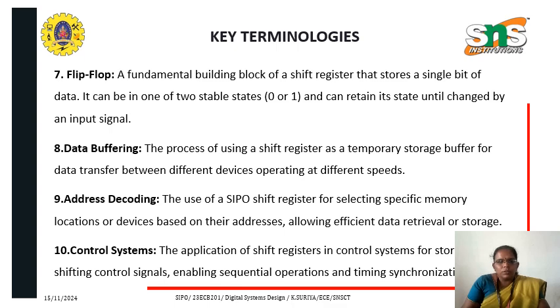It is a process of using a shift register as a temporary storage buffer for data transfer between different devices operating at different speeds. There is also the use of the SIPO shift register for selecting specific memory locations or devices based on their addresses, allowing efficient data retrieval or storage. And the application of the shift register in control systems for storing and shifting control signals, enabling sequential operations and timing synchronizations.